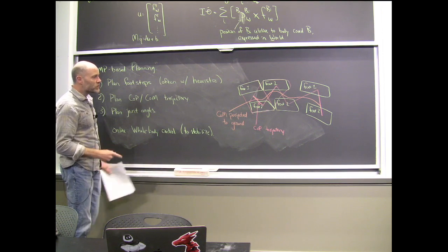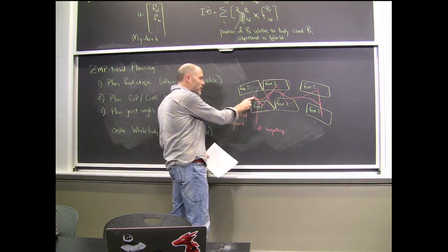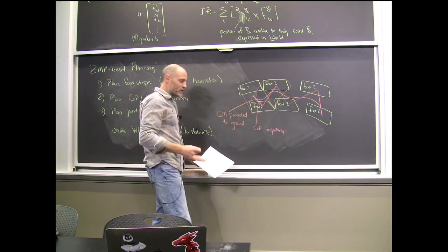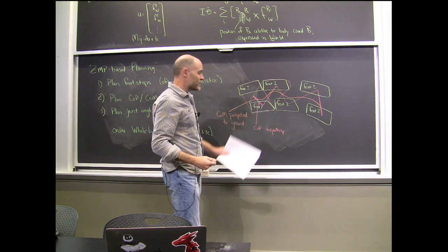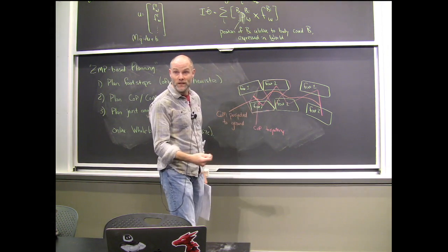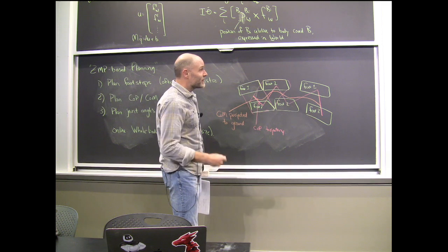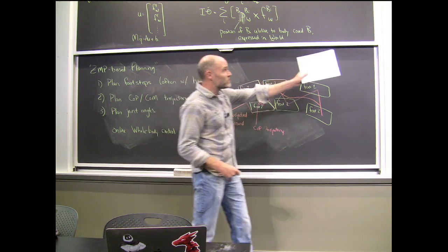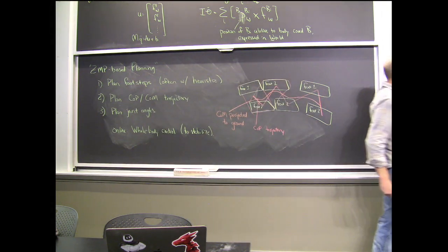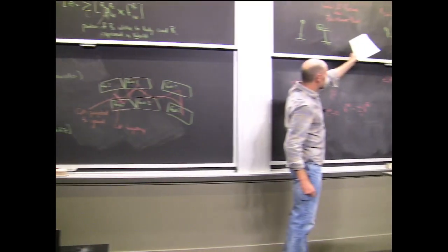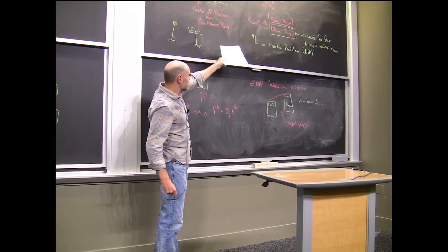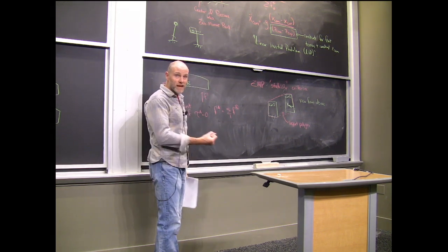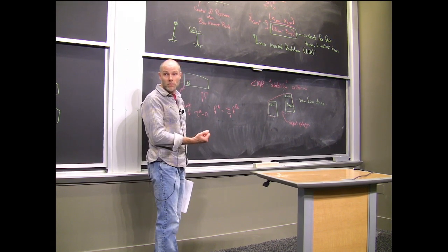There's a very nice thing here. Let's say you've got a center of pressure plan and a center of mass plan, and you're executing and you see that your center of pressure is a little bit off what it wants to be. It turns out that because the relationship between the center of mass and center of pressure, given the assumption of constant height, is linear, or affine because it's got an offset term, you can actually stabilize your center of mass trajectory as an LQR problem.